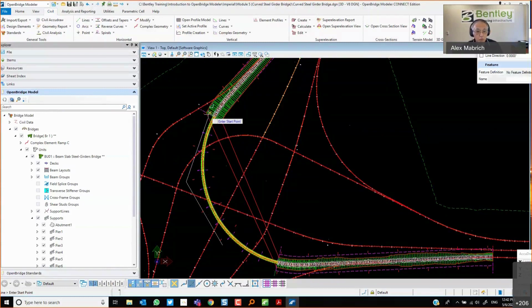So I can just do variable constraints, the same on the deck, and say, make it follow that line. And the deck will just vary along the line that you place. And it could be following the horizontal, but if you attach a profile to that line, it will follow the horizontal and vertical pattern, right? So yeah, it can be done. And there are videos on YouTube, in our channel, where we show how to place a variable deck using graphical lines. The other one, we explain it even in the training guides, that you can do it by hard coding a table, right? But then on YouTube, there is a video of that, right?